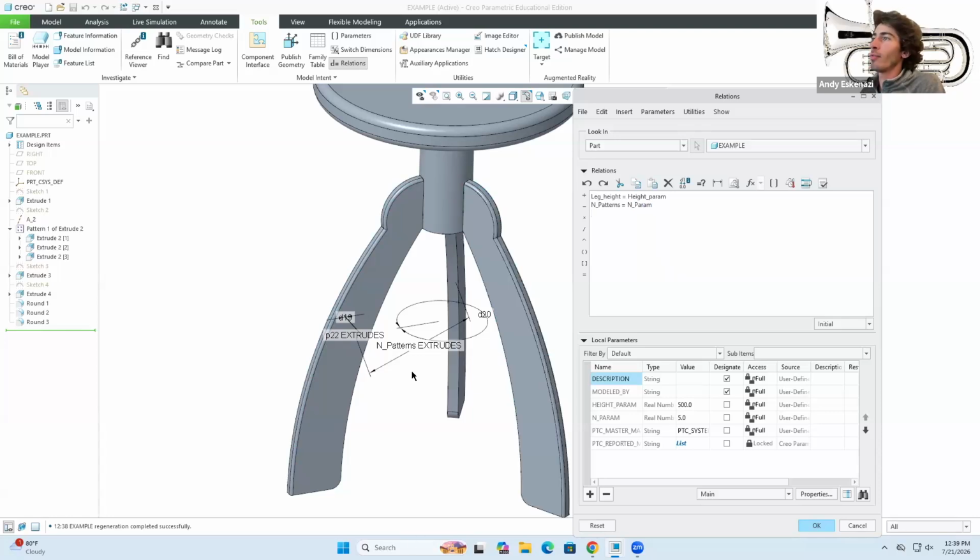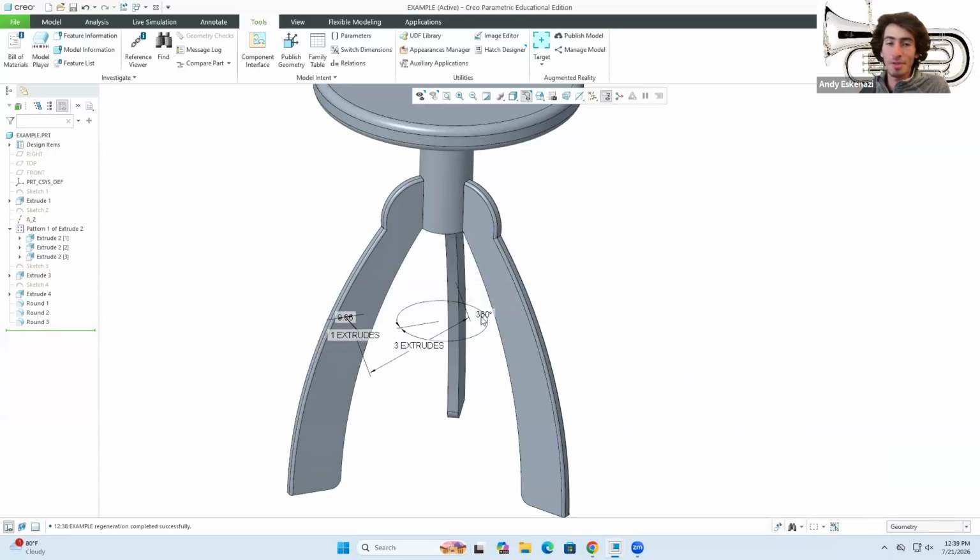And then one fun one in here, I believe it's D20. D20, if I'm not mistaken, is the angular extent. So I might add here D20, I would have to check it, right? But I'm gonna put 300. We'll see what happens. I do not know. But I'm gonna go here to execute. Everything has been successfully verified. I go here to OK. Yes, I believe that was the angular extent.